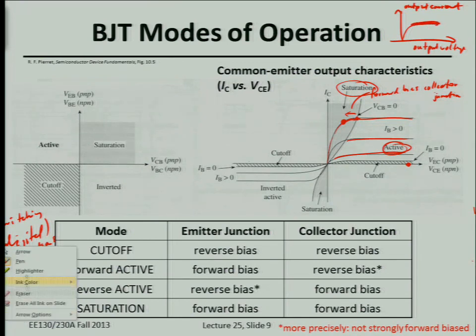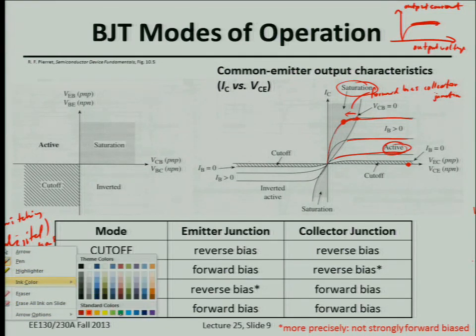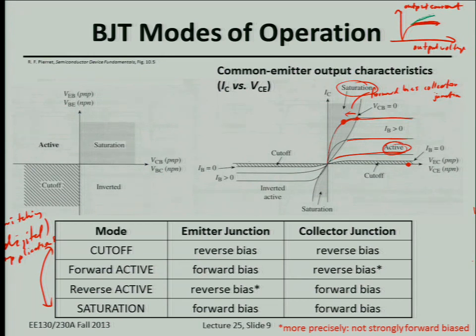So remember I had mentioned the small signal model, that if you have a slope here due to channel length modulation or drain-induced barrier lowering, that slope is actually bad for small signal gain. Okay? So we have the same thing that could happen here. For a BJT, you can actually have a slope here.